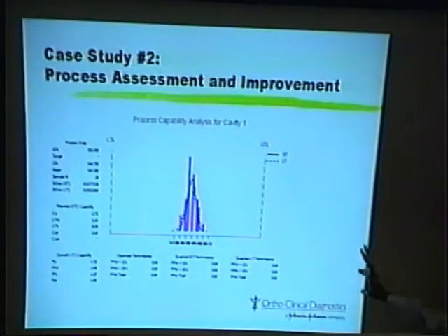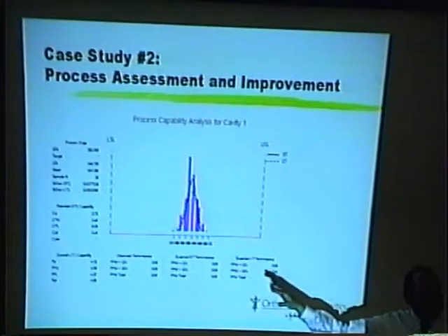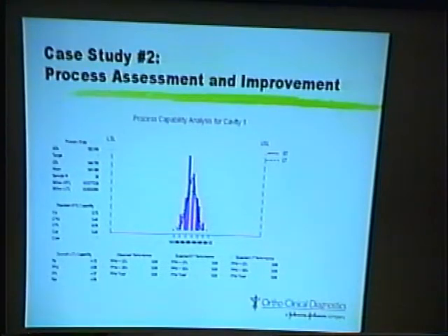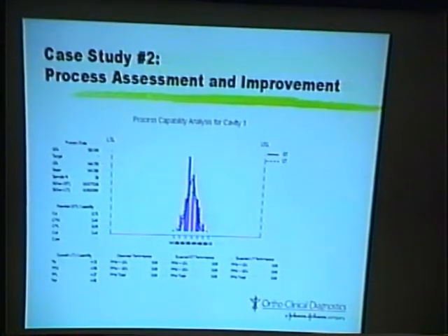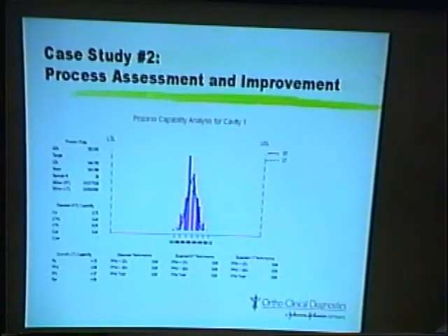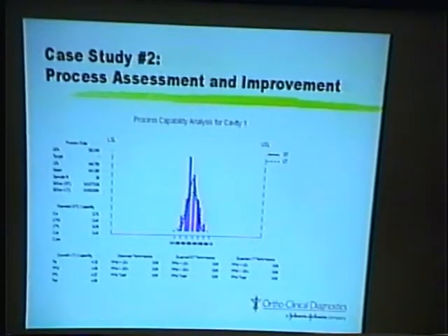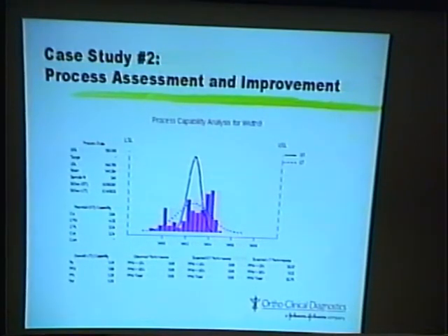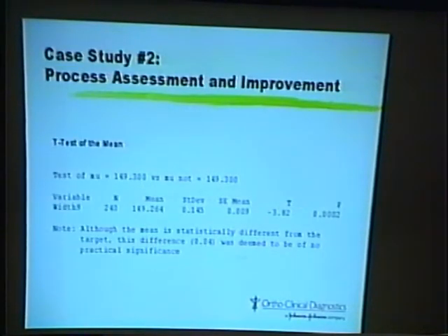parts per million defective. Of course, those estimates are based on some assumptions, normality, etc. So this is just to let you know that one approach would be, then, this appears to be acceptable, but somebody wants an answer. Somebody wants to know what's the before parts per million defect rate versus the after. And do you just assume normality to get a quick answer? Probably not. So just to let you know, you might want to look at this as 8 different populations, one for each cavity. And here's a summary of the entire distribution as well.